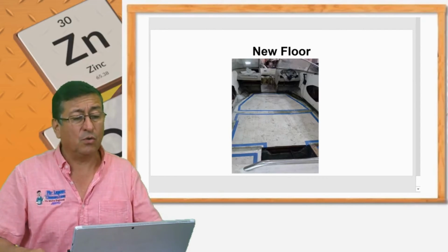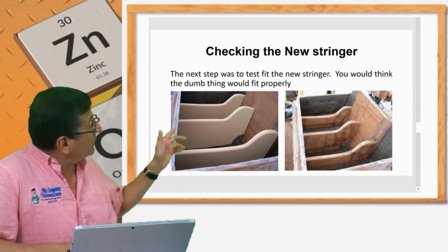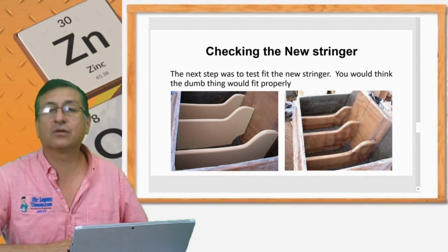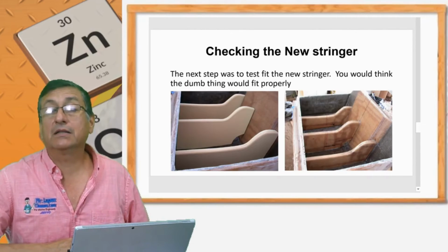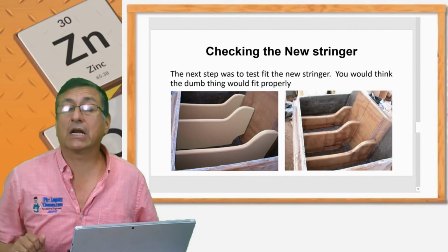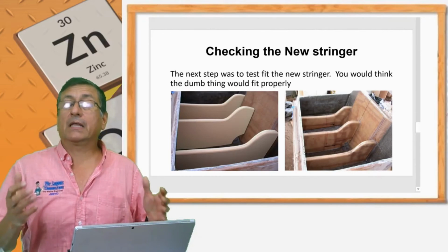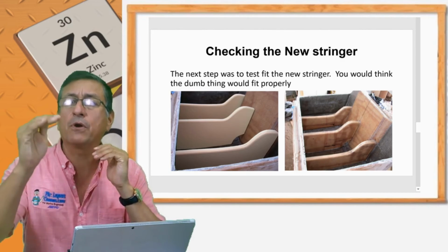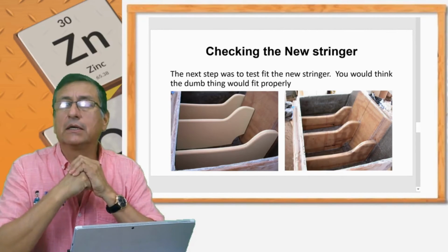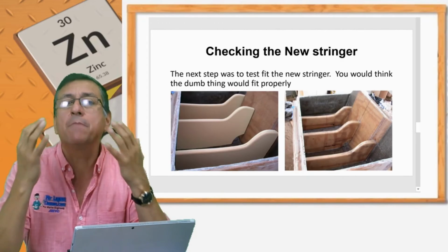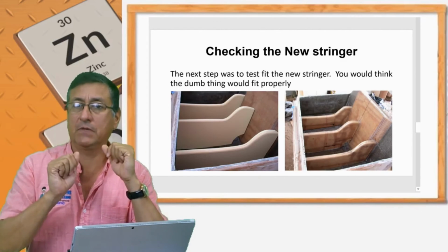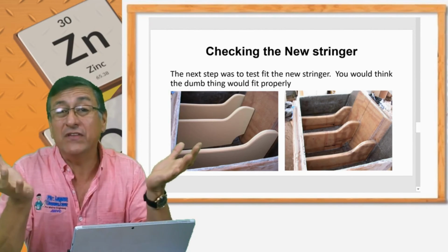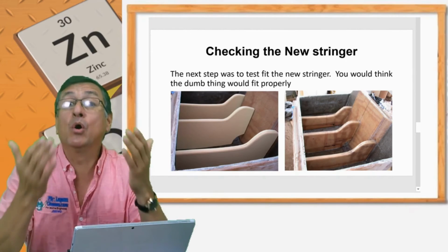This is a great project. We reinforce the transom with the stringers with a special shape on the stringers, and we laminate the stringers. Nice project. This is part of the project that we are going to do in our class of composite materials. But I bring part of that project only to demonstrate that if you select improperly hardware, no appropriate hardware, you destroy the boat. If additionally you have leaks of current, the process of corrosion is accelerated. And at the end of the day, the boat will be destroyed.